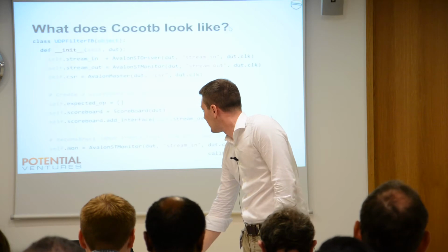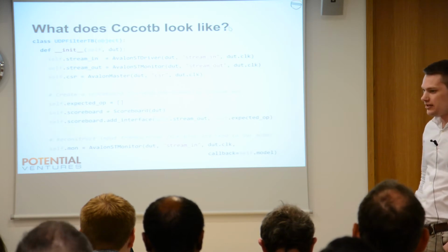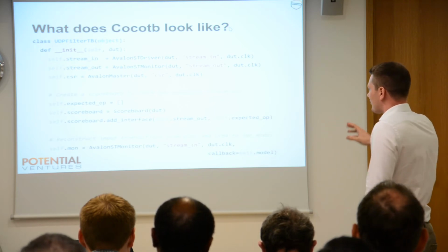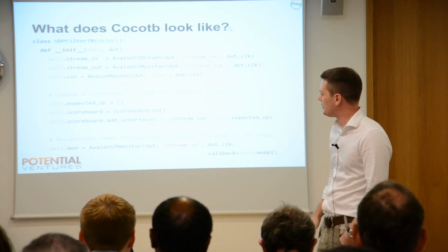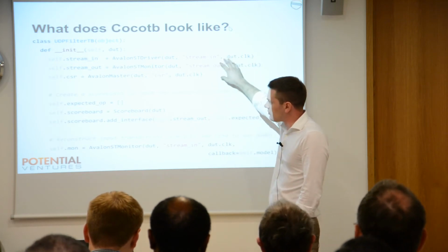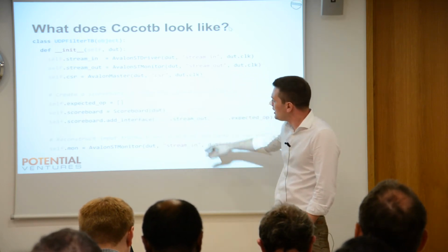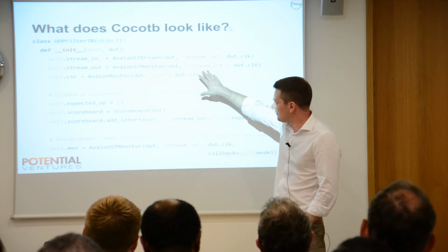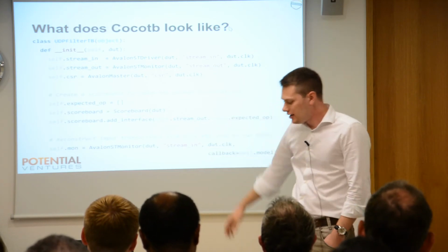Okay, so what does Cocotb look like? This is an anatomy of a test bench. I know it's always a bad idea to put code on the slide because no one reads it anyway. We've got tutorials and documentation on our website if anyone's interested. But effectively, we create a driver and a monitor for some streaming interfaces here. We've got a configuration status register port here. We create another driver for that. We create a scoreboard. We create a monitor that recreates transactions off the streaming bus. And here in about 12 lines, we've created quite a complex test bench.